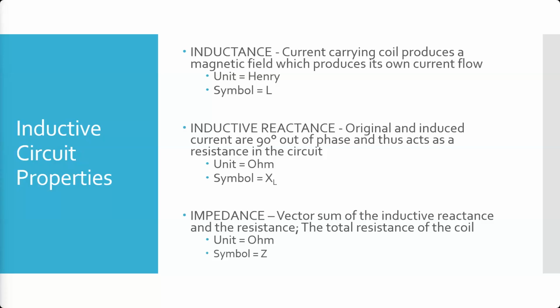Okay. And because of the differences in where the magnetization is occurring, or where the currents are forming, right? There's a current through the wire in the coil being driven by your tester. There's a separate eddy current in the part. That one's going to be 90 degrees out of phase, or if you look at a phase over time, it's going to be offset by 1/4 of the phase time.